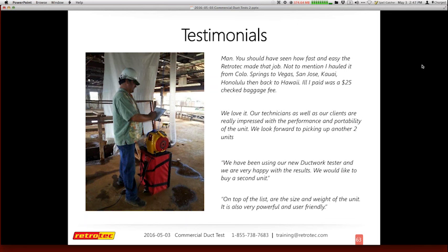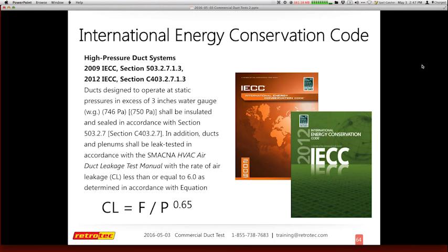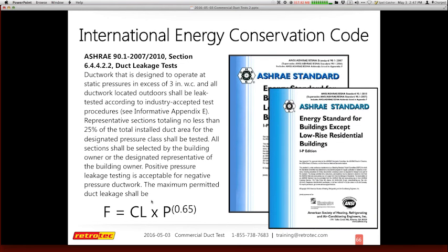When you start the next test, it will start up as a SMACNA test or whatever you've selected. You basically walk through from left to right, just like reading a book, and fill in all the blanks. You can take the data on the job site, and I'm thinking most people will. The important thing is to know what the test pressure should be.